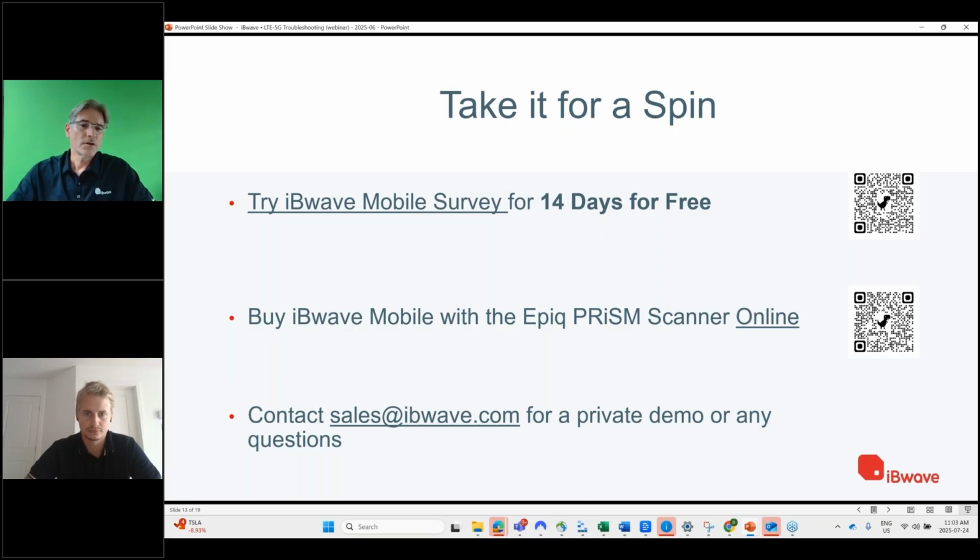Then you would take that survey to design the network, identify the proper antenna positions to be the dominant server inside that building. No interference from outside can, let's say, impact your mobile network inside. And then you install it, and then you do the site acceptance test again with the survey scanner solution, and everything will be integrated in the same IBWave format. So it's a standard worldwide. The survey tool speaks the same language as the design tool, so you can exchange data easily between them.